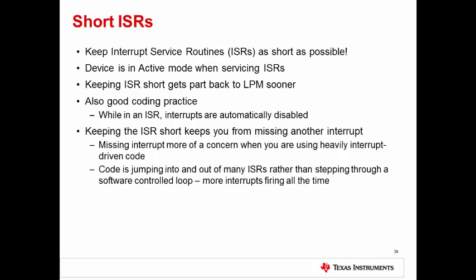A simple system, which is perhaps only waking up from one periodic interrupt, perhaps could waste time in setting unnecessary flags and jumping to the main loop. But a more complex, heavily interrupt-driven system could benefit from jumping quickly to a main loop to keep everything under control, including the watchdog. And by keeping the interrupts short, it ensures lower latency and decreases the possibility to miss interrupt events.